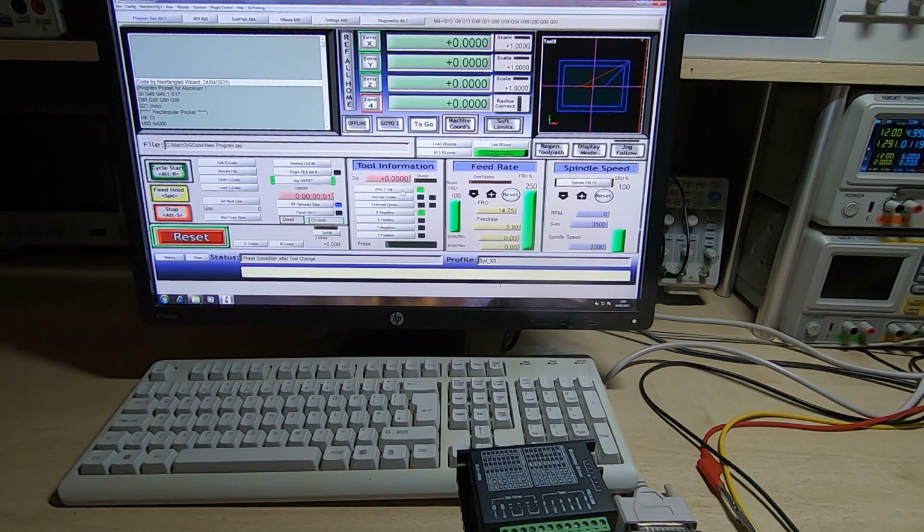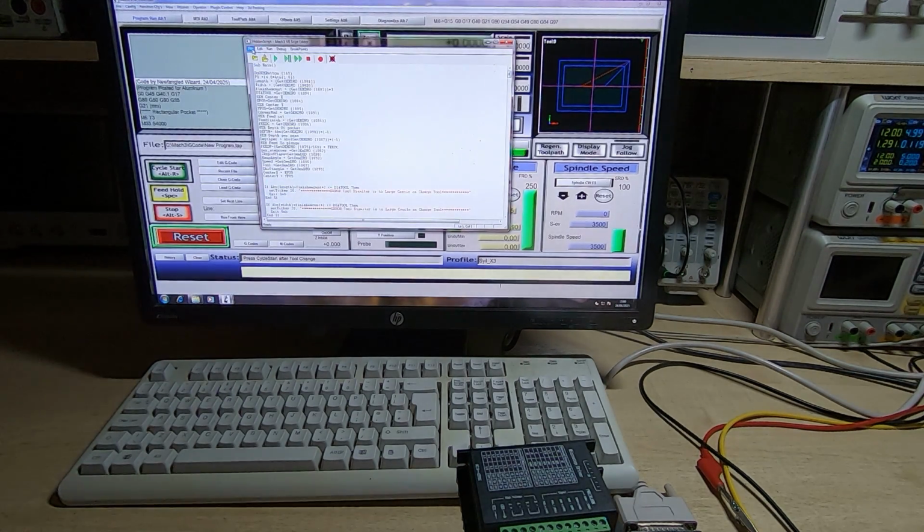So it's run that macro we've just seen. It's zeroed the old tool, stored the G54 fixture location, the Z location for the tip of the tool, and now it's waiting for us to click the cycle start button. When we click the cycle start button, as I said, it runs the M6 end macro. So we'll open the M6 end macro,